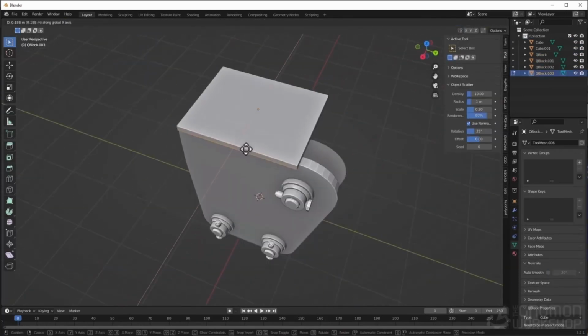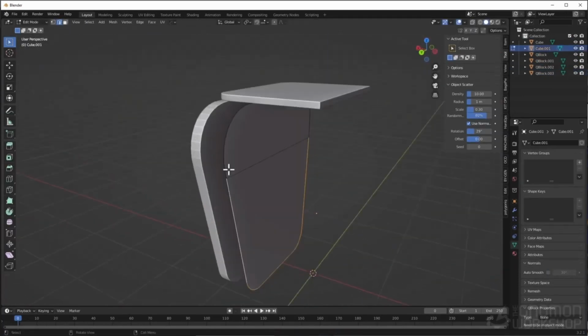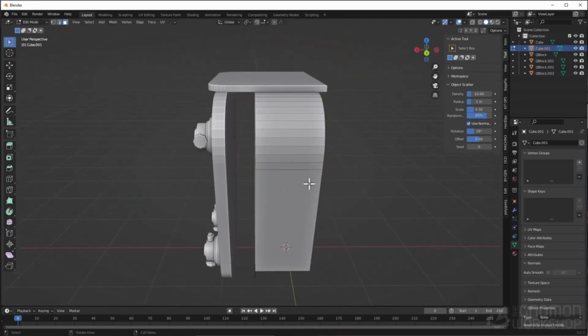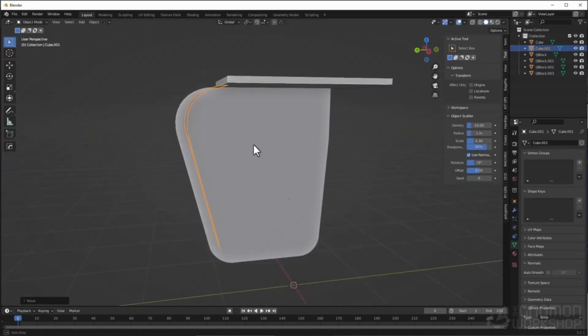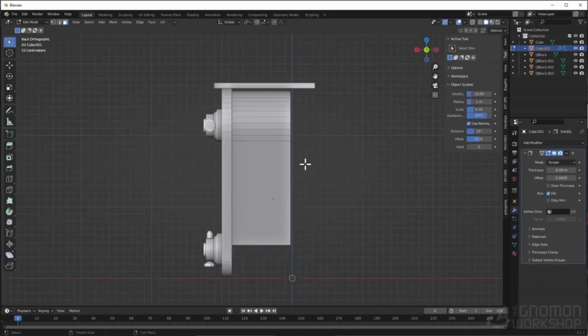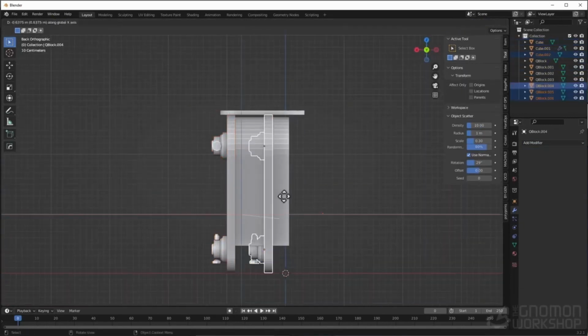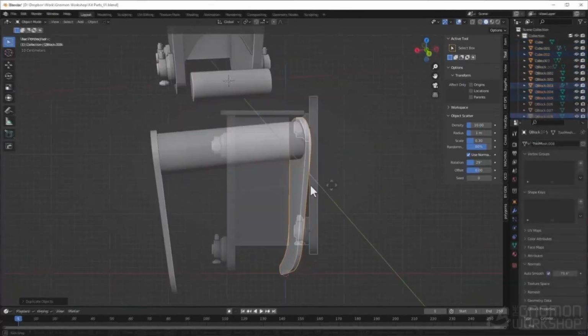It looks like I'm going into an unnecessary amount of detail here, but I can probably use these details on other parts to tie them together. This is the mindset I'm in throughout the whole process. I've added a bit of depth to that flat geometry using the Solidify modifier, which is a modifier I'll be using a lot in this chapter.